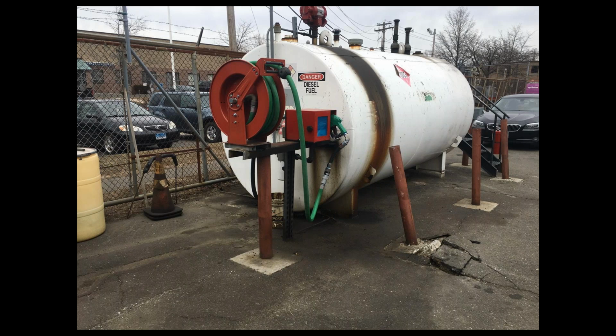And then the second thing is, with a double wall tank, you've got to look at the interstice. In other words, you're checking that interstice for fuel. There are some pretty cheap things on the market that you can put on that tank, and it will give you a visual cue whether or not there's liquid in that interstice. Because if you have a release from the inner tank to the outer tank, now we consider that a single-walled storage tank with no containment.